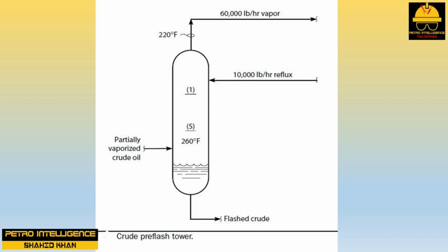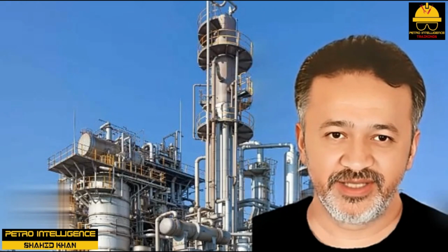The reduction in the tower top temperature of 20 degrees Fahrenheit does shrink the gas by about 3% as a result of the temperature reduction, so that the net effect of raising the reflux rate is to increase the gas volume through the top tray by 15%, that is 18% minus 3%. This results in a substantial increase in the top tray pressure drop, which can, and often does, cause the top tray to flood. This can happen even though the external heat input and feed rate to the tower have never changed.